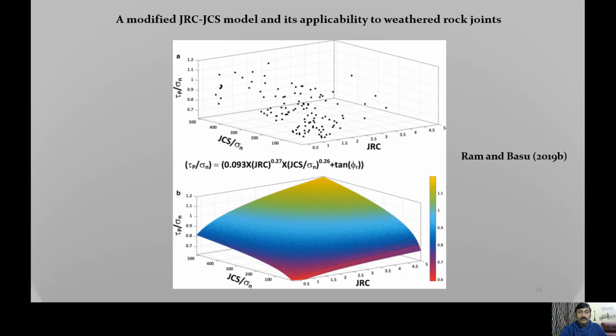In this case, with reference to weathering rates, we simply need to determine or assign the weathering rate of the surface material of a joint surface. Then we need to depend on JCS, which could be indirectly found through rebound hammer values and related dry density, through Deere and Miller equations, and then we can find out the JRC.